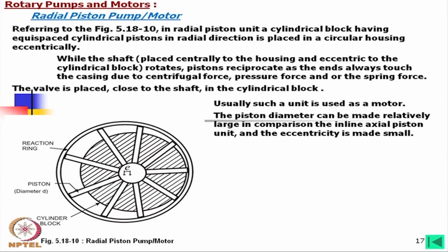In that case, say the dP is 100 millimeter, so total length will be how much? Pi into 100 is about 314 millimeter. Now, we are going to use 7 pistons. So, 7 pistons means totally we need one hole and one space between the two holes.